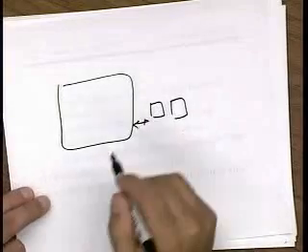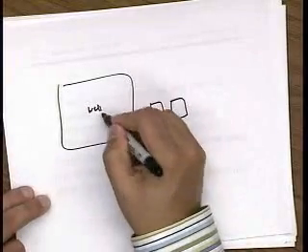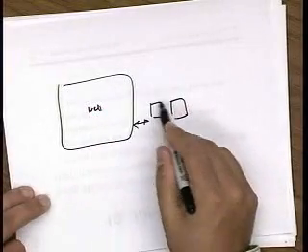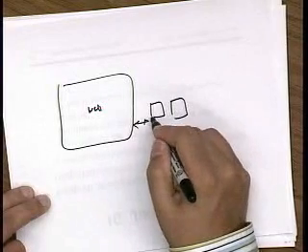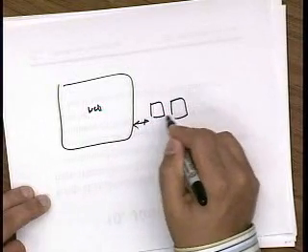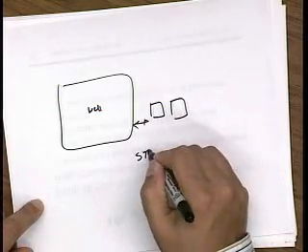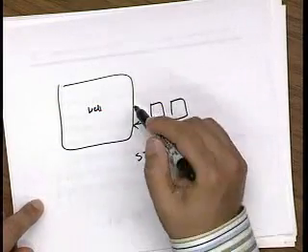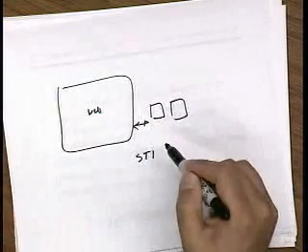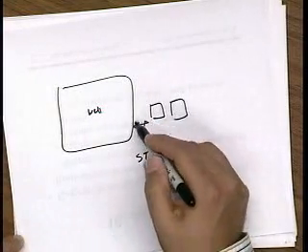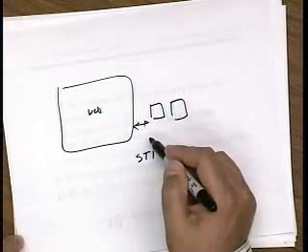This distance, let's say this is a well, will impact these devices, and the devices that are closer to this well will feel more stress than devices far away. This is called STI, and it's basically the oxide, the trench isolation, that's causing stress on these devices.